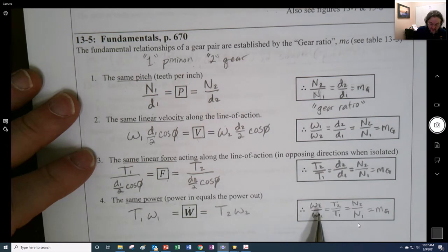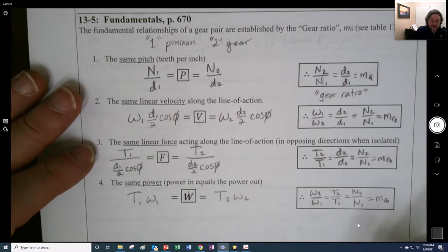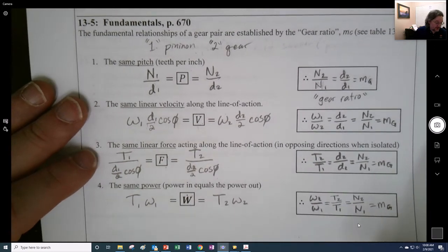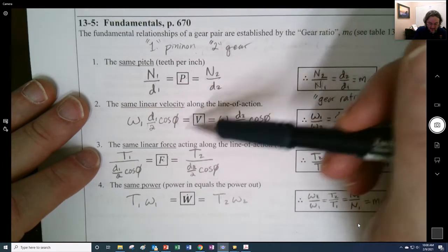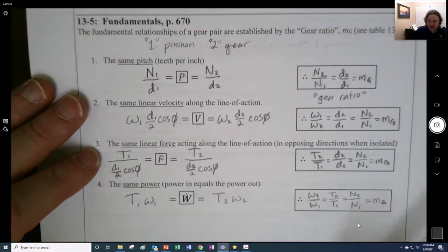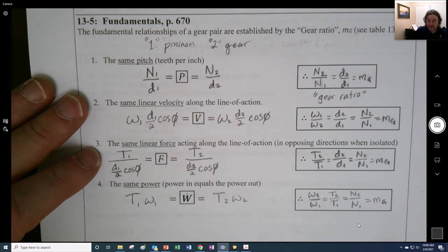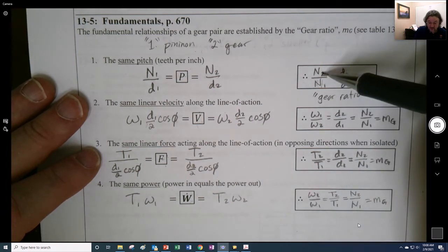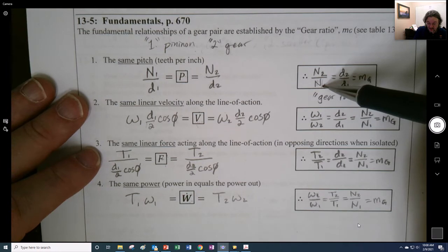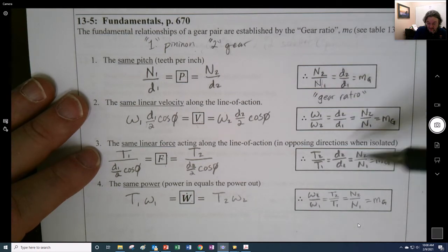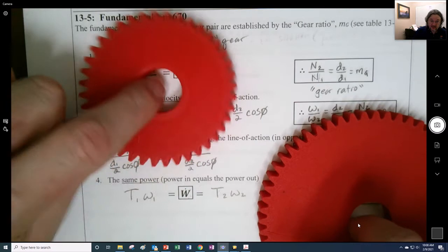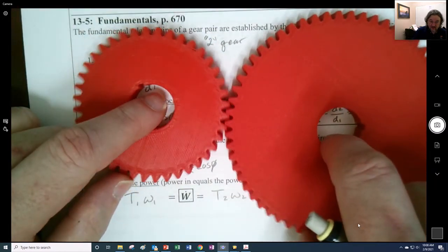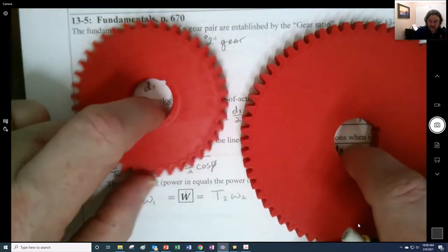So there you go. There's the fundamental relationships between gears. And the best thing to do is to work through and find what I think to be able to keep these straight about what the cause and effect of having a number of teeth to each other, right? So more teeth to lesser teeth right there is going to reduce the speed, right? So we're going to end up having a speed reducer, and it's going to increase the torque. So high speed, few teeth, lower speed, more teeth, less torque, more torque.